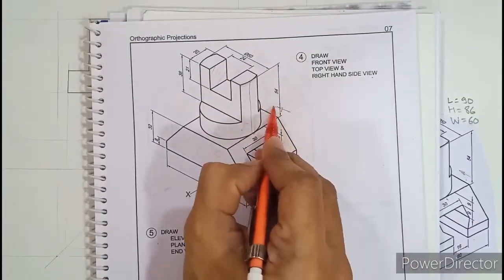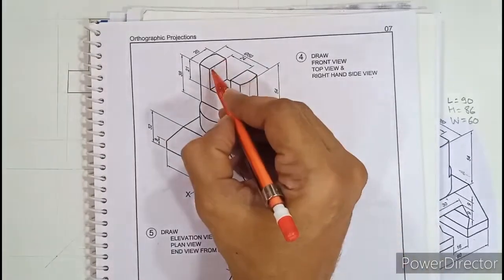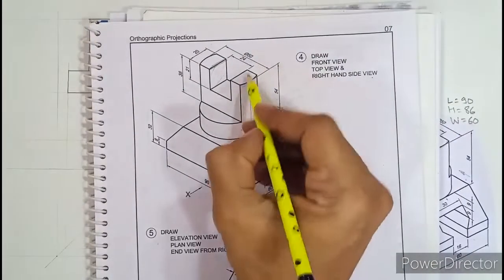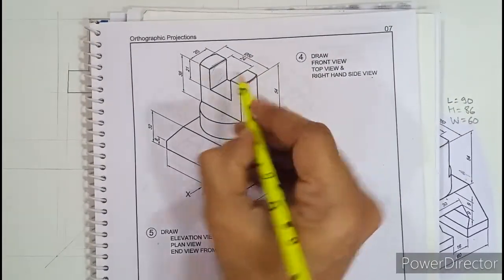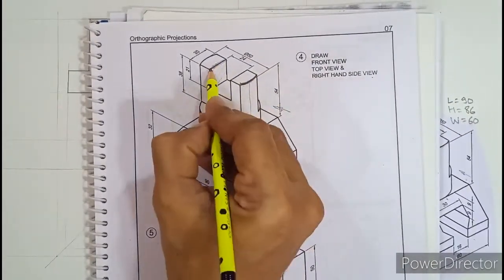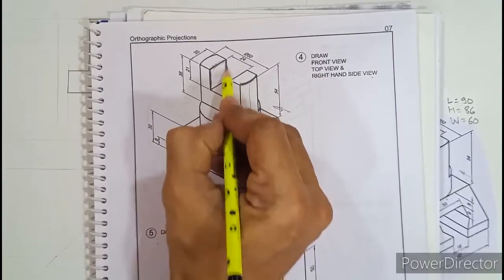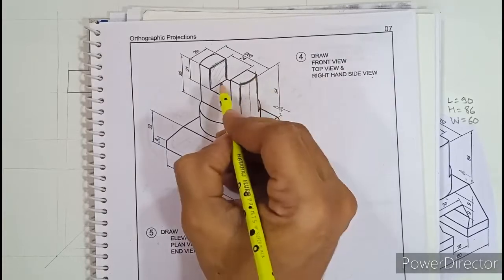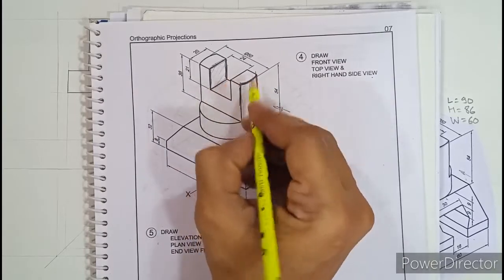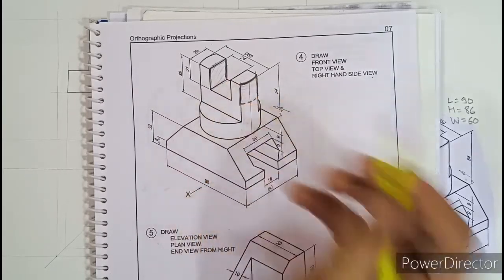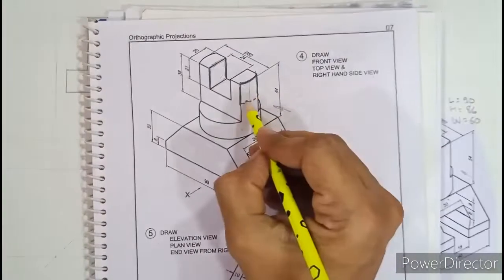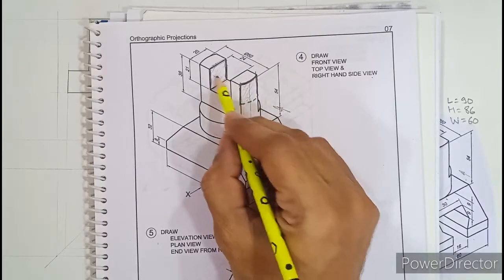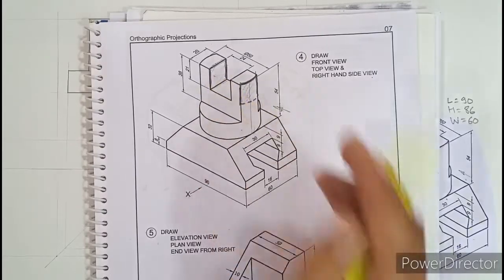When you look from this side, you cannot see that surface. So this horizontal edge of the surface, if you observe thoroughly, it overlaps with this curve, isn't it? So both of them overlap. This vertical edge and this vertical edge overlap with these two extremes. What doesn't overlap? It is this horizontal line, and for that you need to show hidden line. So once you draw hidden line, this area resembles the hidden surface. So that is how you have to understand.